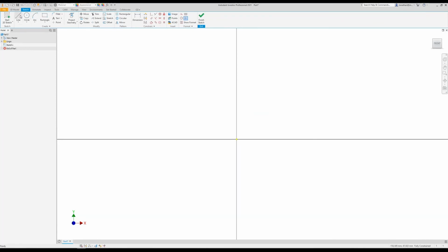So let's go and draw a line. I'm going to go up at an angle, and you'll see when I go down, it's obviously snapping perpendicular. I maybe want it to go here. Now this one I want it to go up, but at a different angle. Now it is snapping, and when you've got a lot of lines, there's a lot more things that the program can snap to. I don't want that to be parallel. I just press Control.